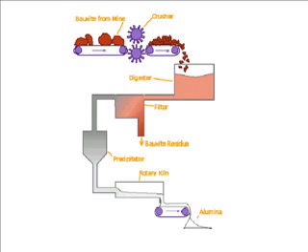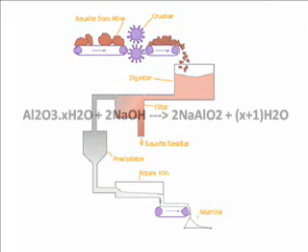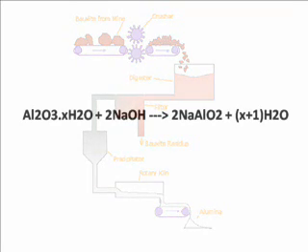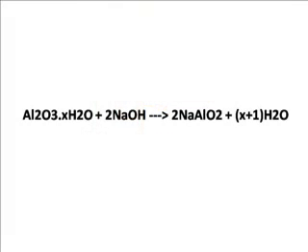To further explain the Bayer process, we can break it down into three stages. The first is extraction. The hydrated alumina is selectively removed from the other insoluble oxides, as discussed before, by transferring it into a solution of sodium hydroxide. And then, as you can see, the chemical equation is presented above. This process is much more efficient when the ore is reduced to very fine particle size prior to the reaction occurring.